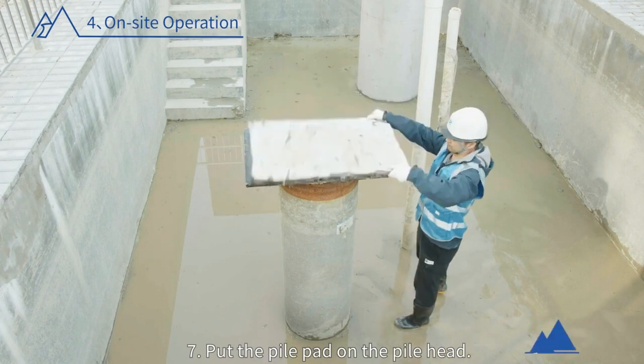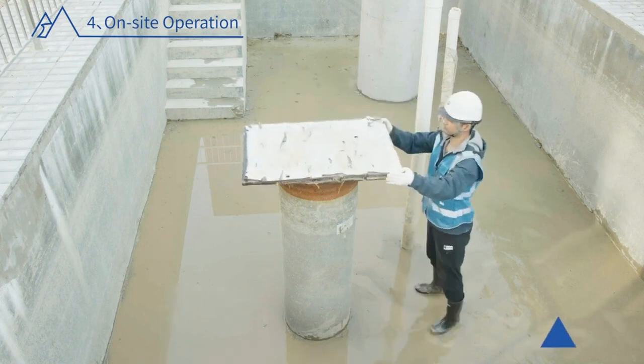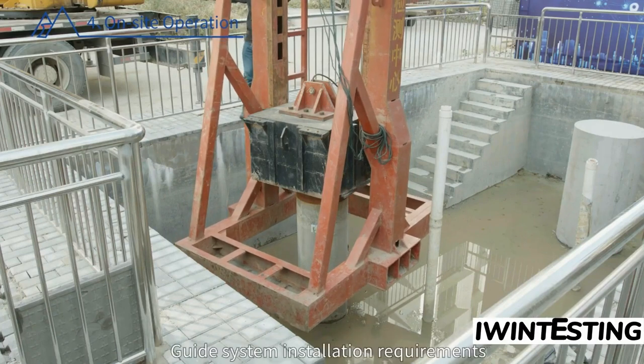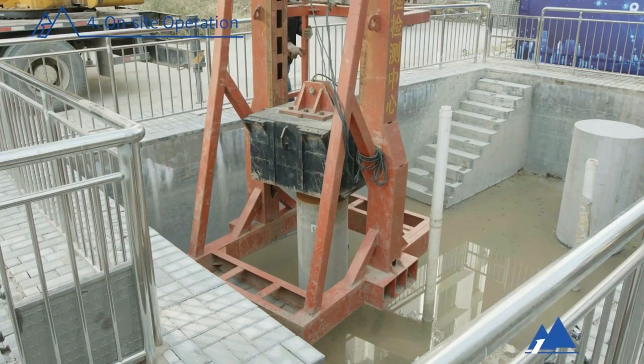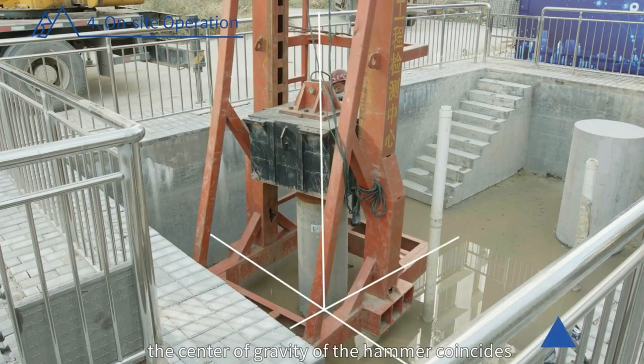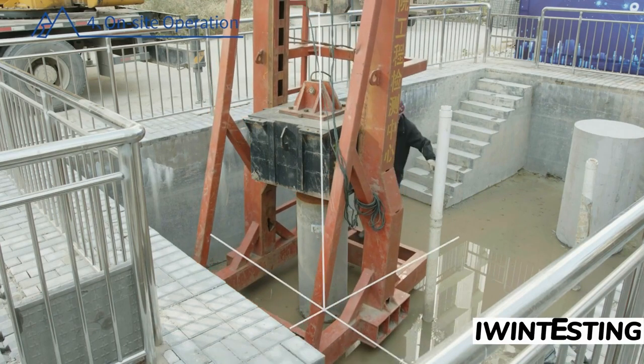7. Put the pile pad on the pile head. 8. Install the heavy hammer and guide frame. Guide system installation requirements: the base is stable, and the center of gravity of the hammer coincides with the center axis of the pile.